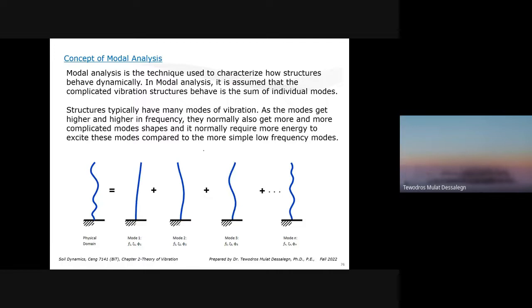Concept of modal analysis. Modal analysis is a technique used to characterize how structures behave dynamically. In modal analysis, it's assumed that you may have a complicated vibration of a structure like this. This looks irregular. What modal analysis is saying is that this complicated response of a structure for a seismic motion or anything is actually the sum of multiple modes.